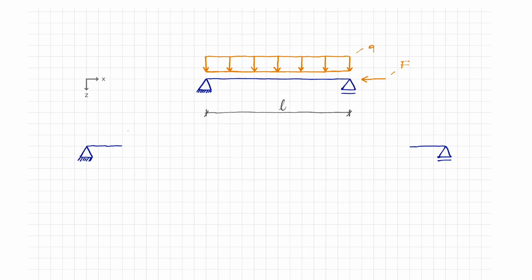First, we cut from left to right. This is the case of the positive side of the section. In this section, the shear force points downwards, the axial force points to the right, and the moment points counterclockwise. It is about the positive forces in the positive side of the section.